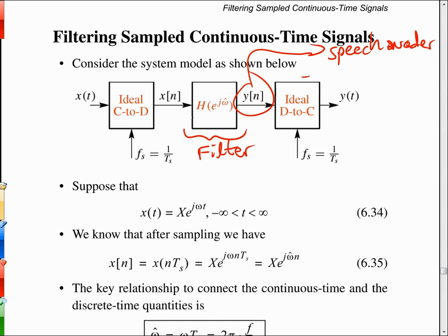Nominally, you could say speech sampled at 8 kilosamples per second, and nominally 8 bits per sample, would be 64 kilobits per second to send that speech waveform in a digital medium. So the airwave is encoded and sent through some analog modulation scheme, but actually what we do with the speech encoder is compress it in real time using what's called a speech vocoder. Vocoder means coder and decoder together, but it's a pair of circuits or a pair of systems. So the encoder is at the transmit side and the decoder is at the receive side.